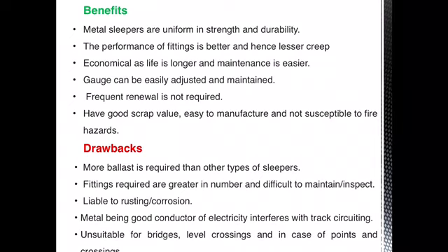Metal being a very good conductor of electricity will sometimes interfere with the track circuiting. These are very unsuitable for bridges, level crossings, and in the case of points and crossings. And these are suitable only for stone ballast. So if you are using any other ballast layer, the use of metal sleepers is not advisable.